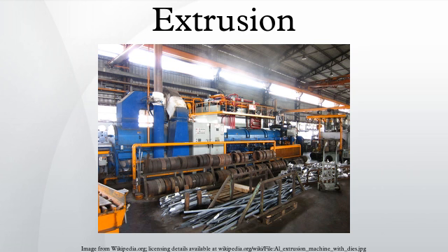The fluid can be pressurized two ways. Constant rate extrusion: a ram or plunger is used to pressurize the fluid inside the container. Constant pressure extrusion: a pump is used, possibly with a pressure intensifier, to pressurize the fluid, which is then pumped to the container. The advantages of this process include: no friction between the container and the billet reduces force requirements.